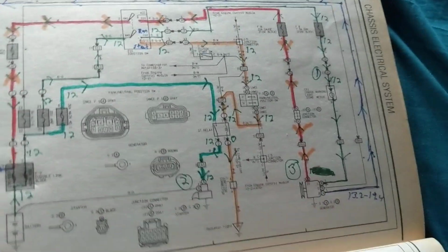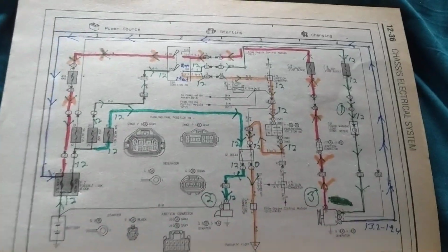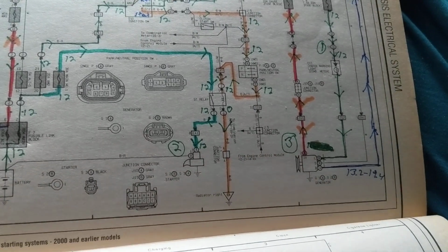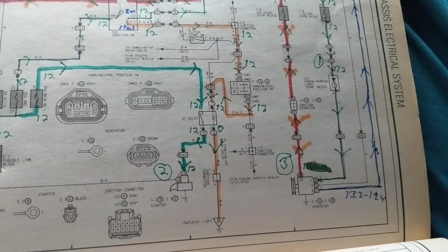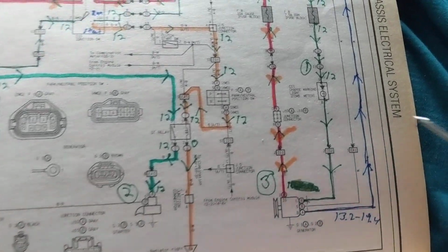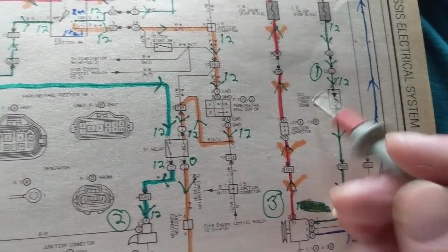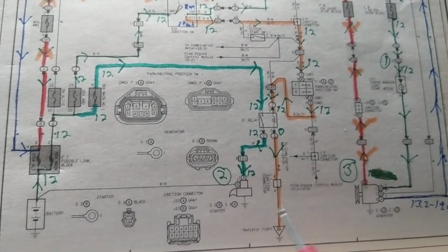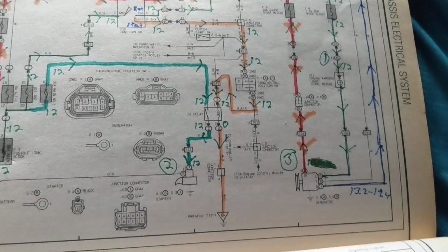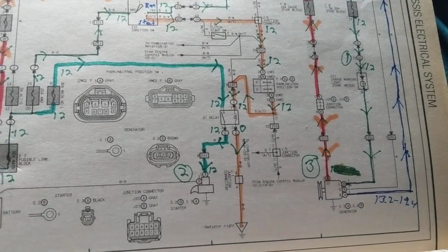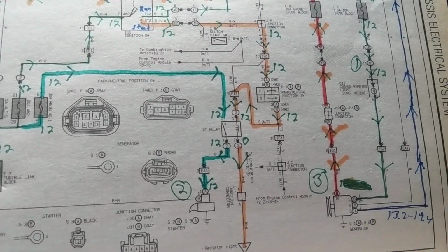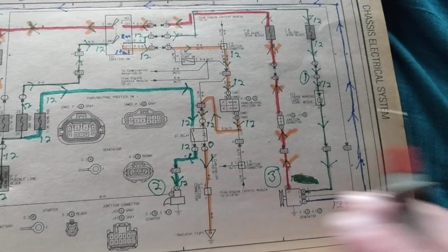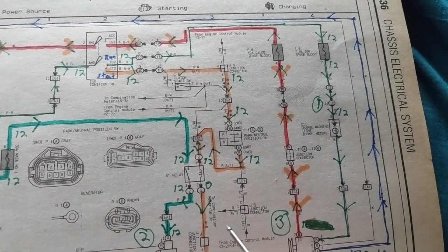Okay? Now, the question. Let's challenge our troubleshooting skills. First thing is, you turn the key in the run position. Right? All the lights come on. As soon as I see it, I see the charging warning light come on, or the battery light come on. What does that tell you? Are the fuses good? Remember, without even putting a multimeter, use those devices, that initialization test to tell you something. Off the bat, that tells me a couple of things.